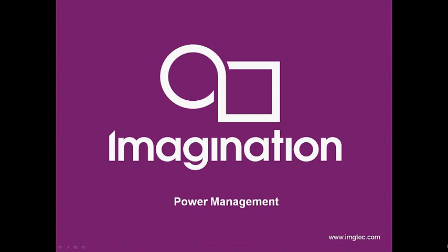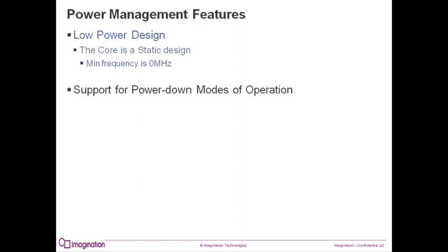This section of the course covers the power management of MIPS cores. Power is a factor of the clock frequency. The lower the frequency, the lower the power. The cores are designed to run down to a zero clock. They can do this because there's a mechanism to wake them up through an external pin interface.